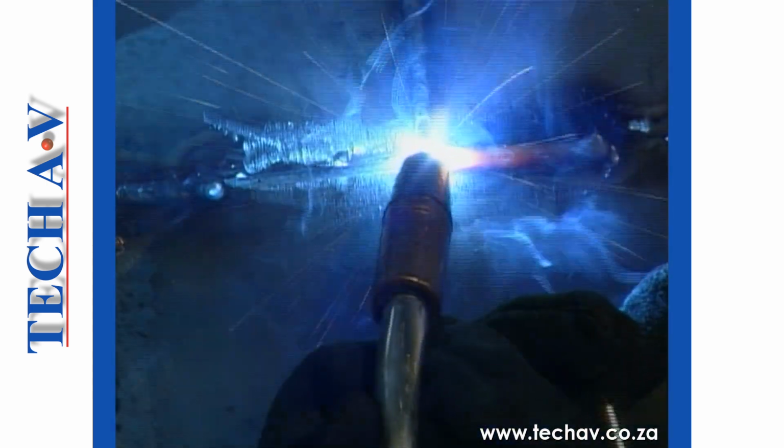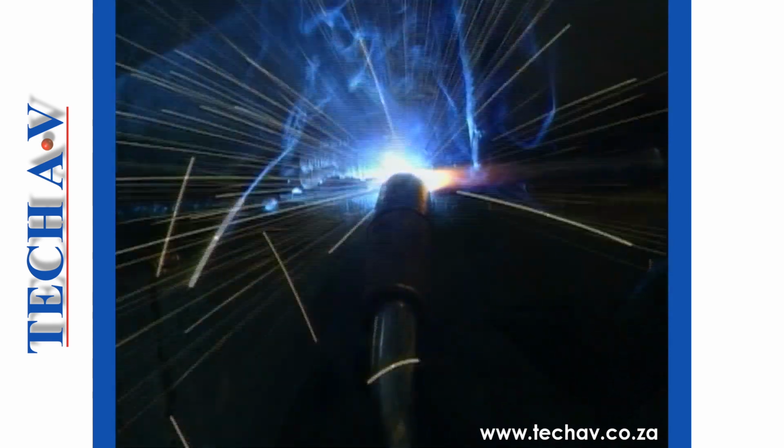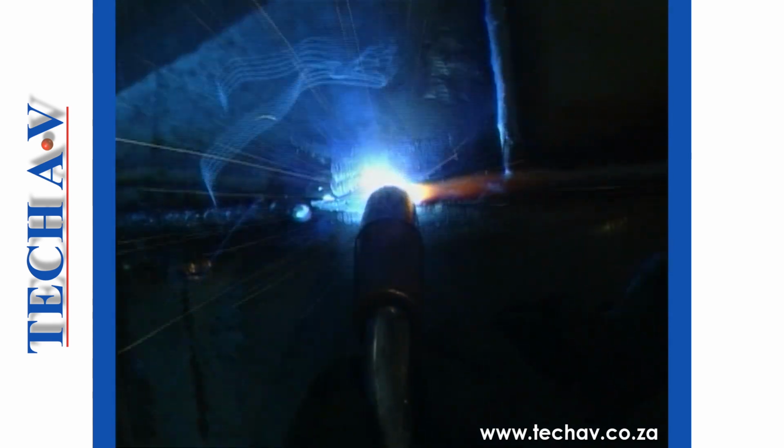The pulsed process produces a cooler weld than conventional spray, and is therefore suitable for the welding of thin metal and out-of-position operations.